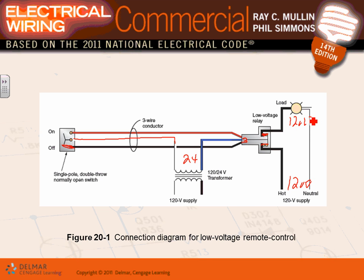By pushing it, the way these relays work, you push it, you energize the coil, it pushes 2 contacts to close, and there's a spring that holds them closed. Now, if I'm going to turn it off, Adam, all I have to do is turn these on here. When you turn it on, you energize another set of coils. This will pull them back, and my light is off. This is the heart of the low voltage system, guys.